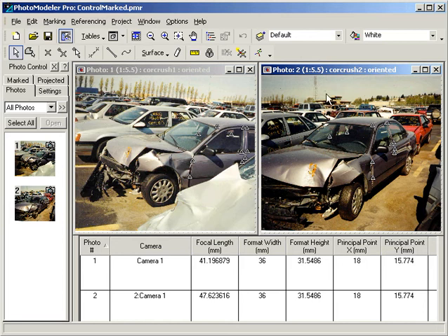The photo table shows changes in the camera's focal length. Each of the photos has solved with a different focal length. In certain cases, you may want to solve for the principal point. This may be necessary if you think the photographs have been cropped and images are off-center. Solving for principal point requires a very strong set of control points with good coverage and depth on the photo. It is a good idea to start by solving for focal length only first, and check your results.